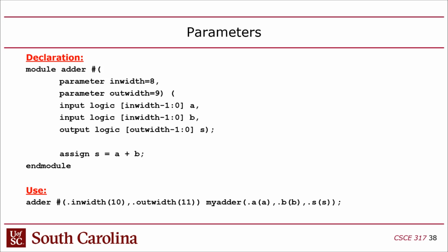Or if I create a CPU cache, I can just set the size of the cache, right? So I could just specify that. And the compiler will take care of basically creating a custom version of this module for the parameters that you set. So this is a compile time thing, just like it is in C++ with templates. So you can set these. Now the syntax here is bizarre. The syntax, this kills me. Okay, so check this out.